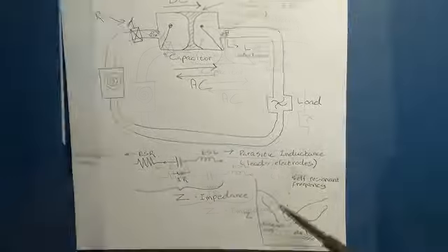If we start at a low frequency, you're going to get a graph that appears like this, where initially you have high impedance, which then becomes lower to a low point, and then goes high again. Those of you involved in oscillators or radio will understand that this sweet spot is what we call the self-resonating frequency, and it's a nice sweet spot to have when we're trying to tune our antennas.